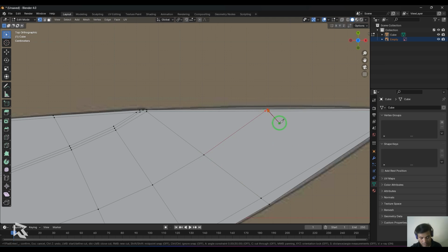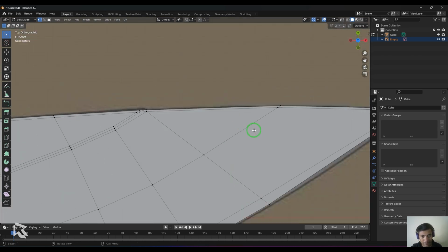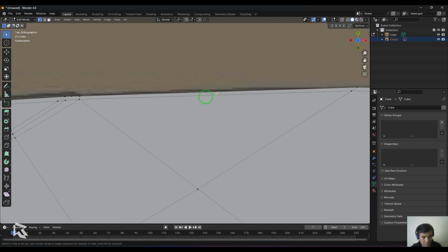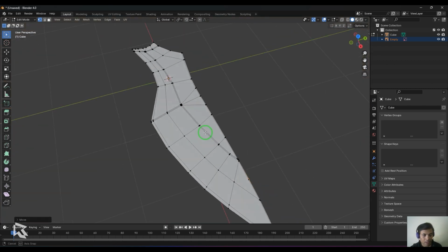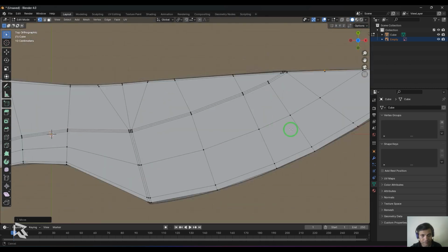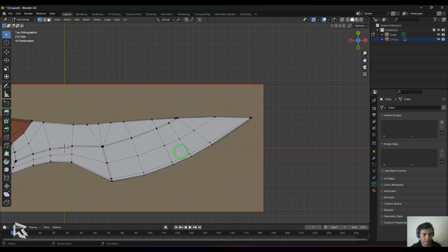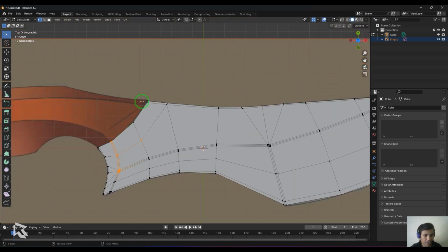and then select, okay, this line is going to add the thickness. So here we ended up in a triangle. So press Ctrl and R, then you get these points, and then that is a quad now. Now why do I have to add this? Let me just actually undo these 2 points. Okay, now let me select all these points again.